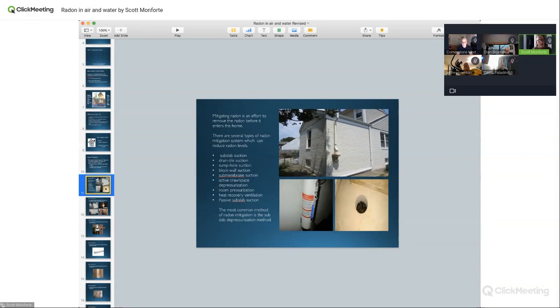If you are a home inspector and you have open window wells, gutters and downspouts that are dumping, full of leaves right by the foundation, that is a problem. If there's a radon system there, especially if it's dumping right in the corner where the radon system is, it's going to eventually work its way down, and I'll get a phone call that I hear gurgling noises.